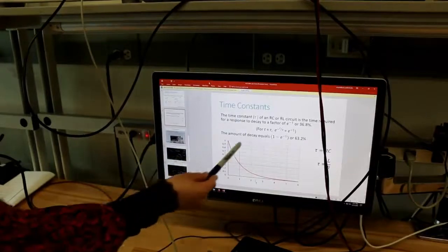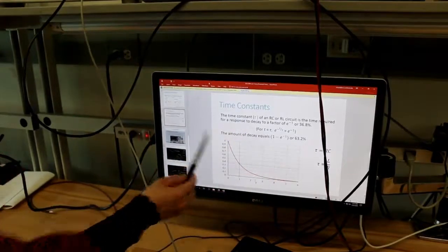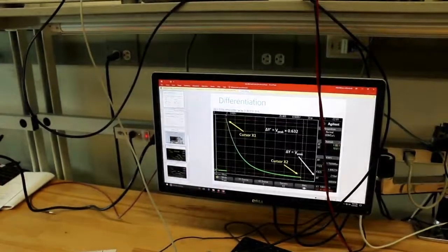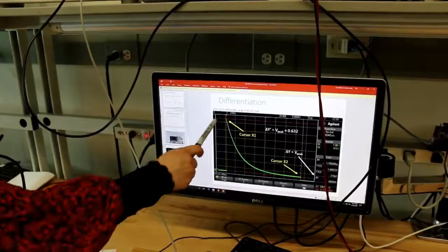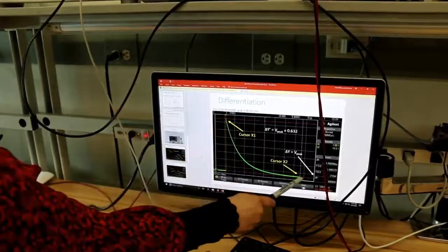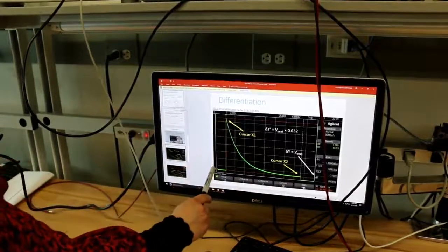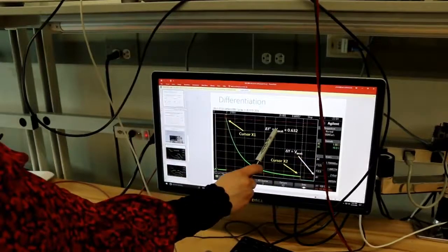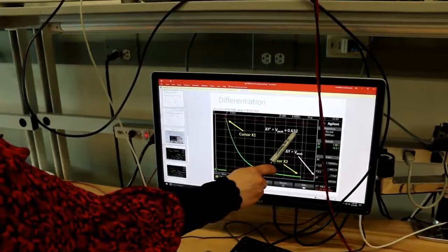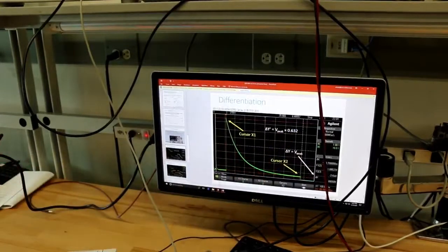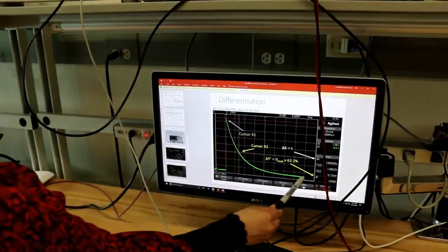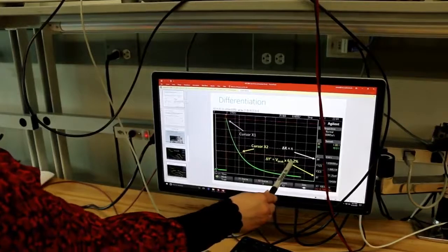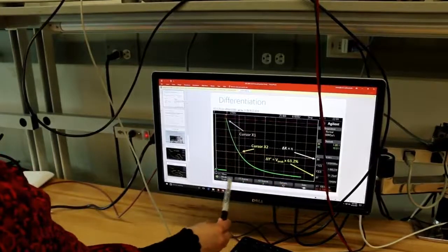So we want to get this response from the oscilloscope, and then use 2 cursors: put cursor X1 at the very top, and put cursor X2 at the very bottom, and then read delta Y, which is the peak value of the voltage. Then multiply delta Y by 0.632, and move cursor X2 to the value of V peak times 0.632. Then delta X is tau.